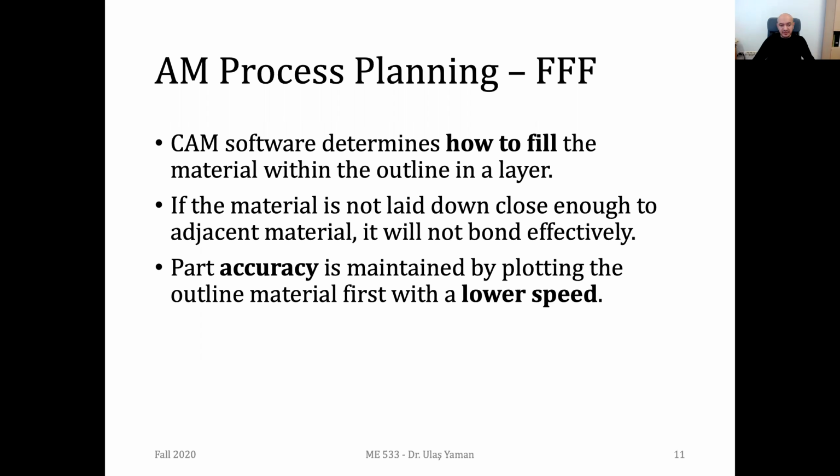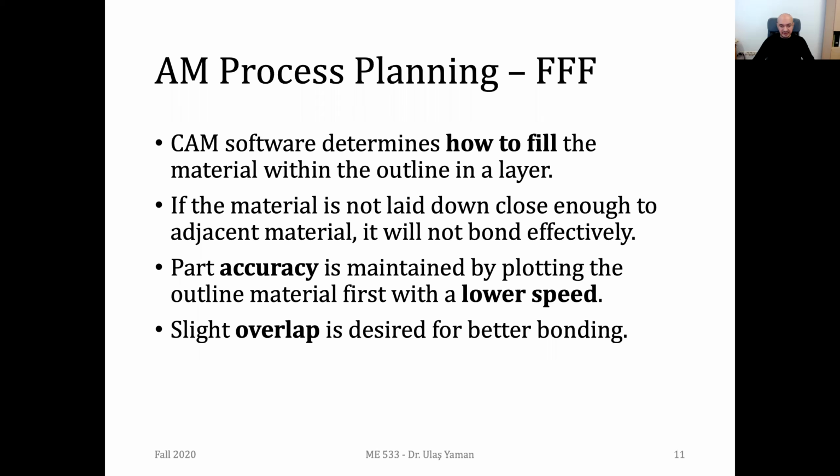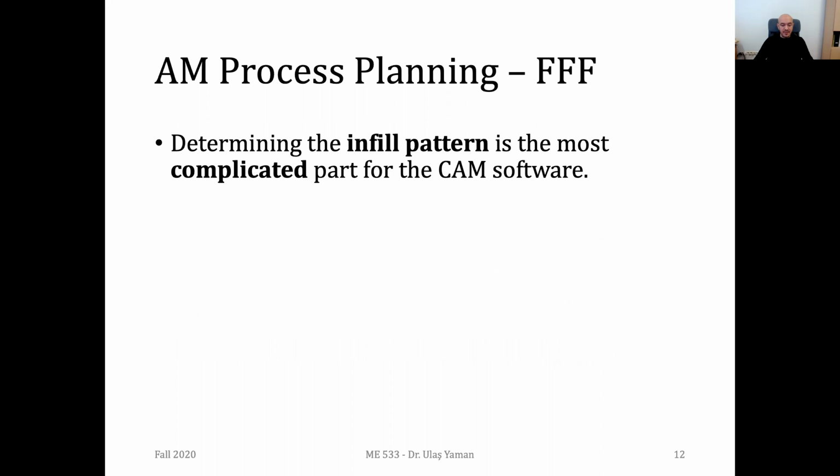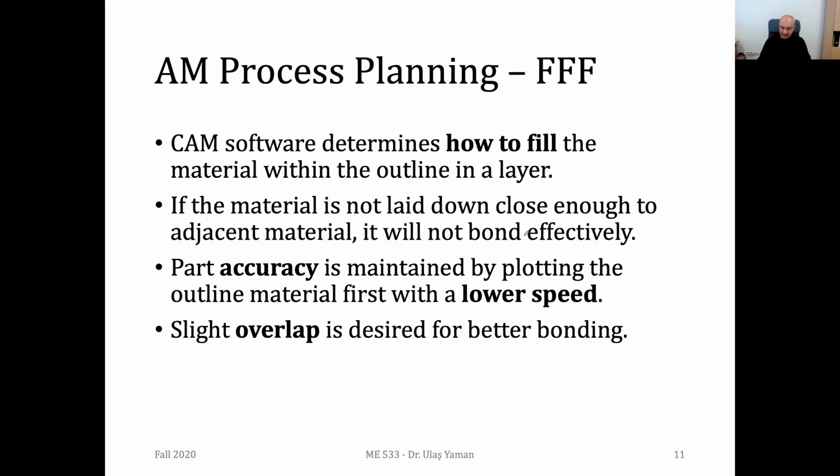And we said that we can produce accurate, high quality parts at lower speeds. Another thing is that to make sure the layers are bonded properly, we need to have a slight overlap between the layers. And even if you want 100% infill inside a layer, assume that this is the top surface of a layer, and you want to fill the interior of this layer completely, then you may have again a slight overlap between these